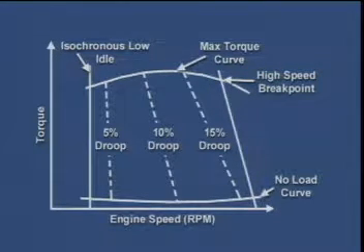Each alternate droop setting provides the ability to select the high-speed governor breakpoint speed, droop percent, and the isochronous breakpoint speed. Droop percent at minimum and maximum throttle for the all-speed governor is also adjustable. The breakpoint speed determines the position on the engine torque curve where the high-speed governor will start to limit engine torque output.